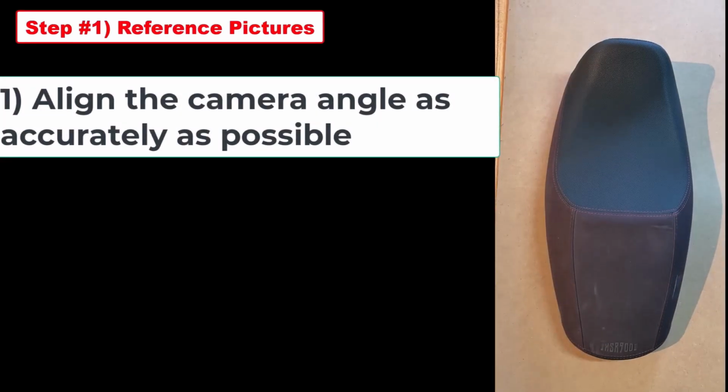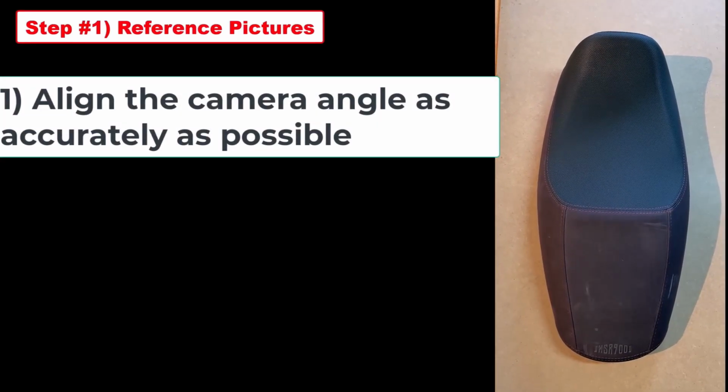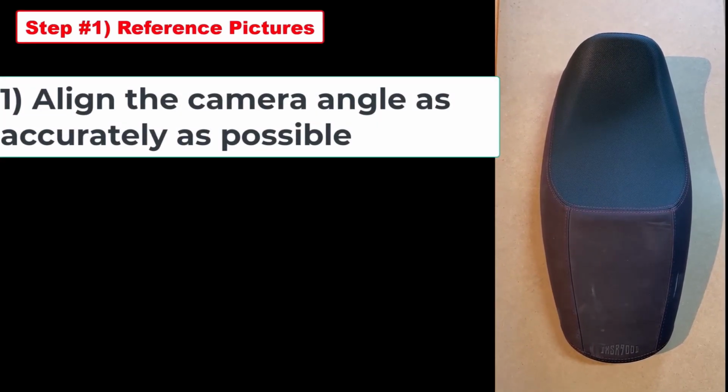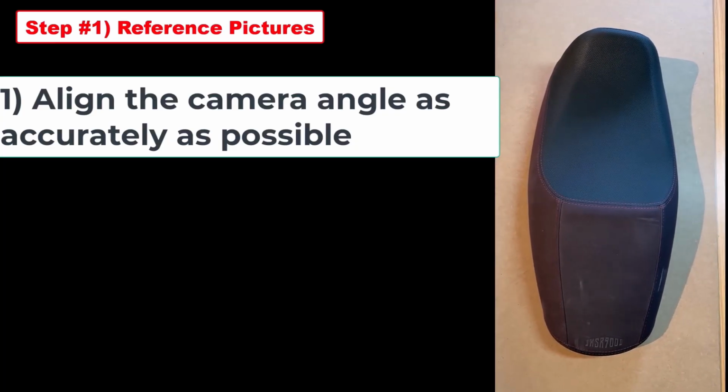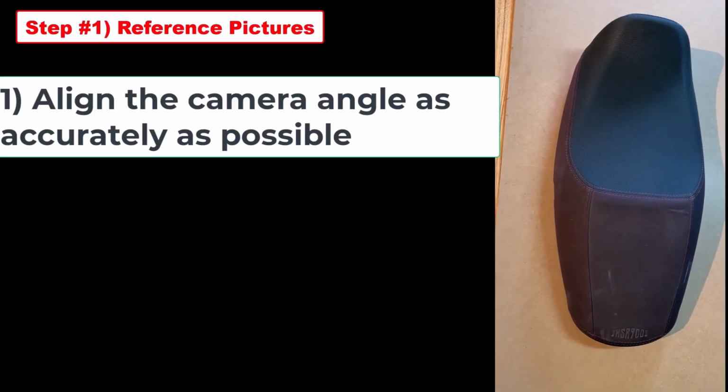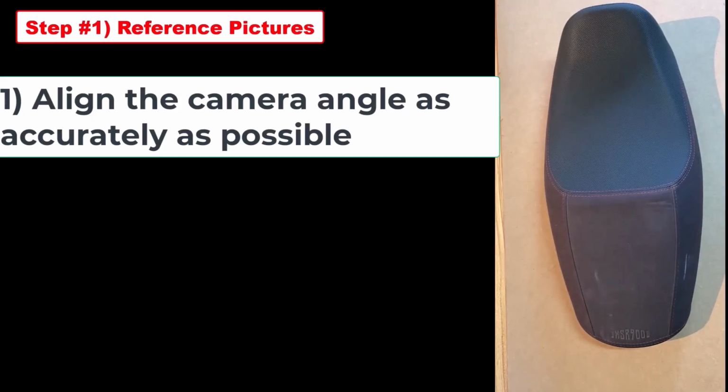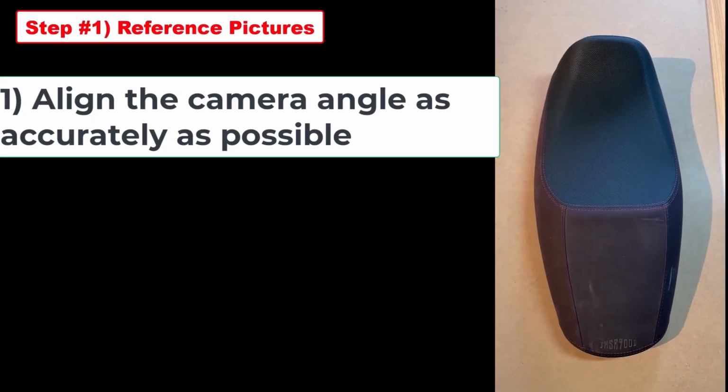Step number one is taking your pictures, and I have a few recommendations here. First, you really want to take the time to set up good reference pictures because it's going to save you a lot of time and get you a more accurate model in the long run. But the best way to do it is by carefully aligning your camera angle to match the sketch planes that you plan on using in SOLIDWORKS.